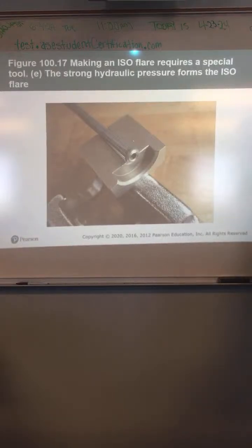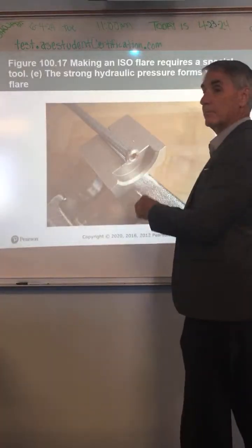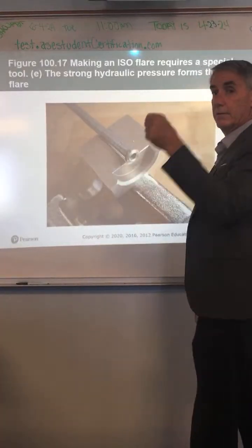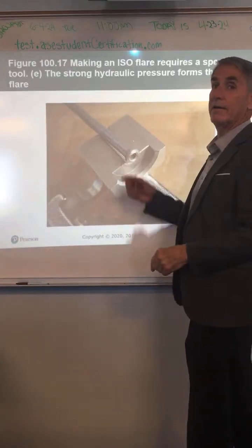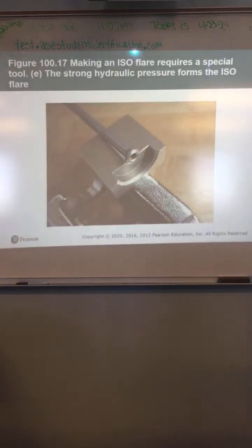Here's the important part. Before you do this, make sure you put the nut on here to tighten it up. I've seen people do this and then they forgot to put the nut on there, and then you gotta cut it off and do it all over again because you can't get the nut on there.